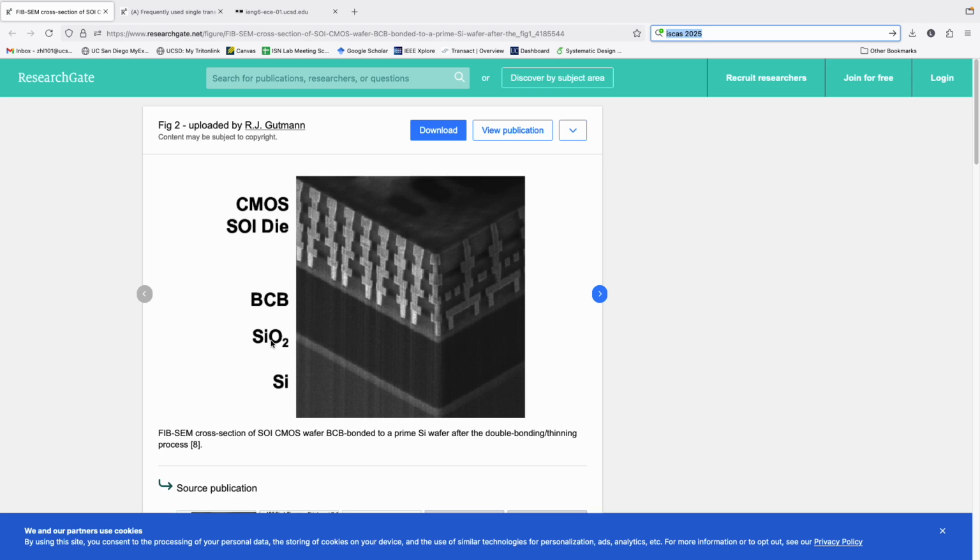On the bottom is the silicon, and this is the silicon dioxide for insulation and whatnot. Up here, these Lego-like ladders are the cross section of the metals that you build in circuit. If you think about them, these are literally just metal strips laying on top of each other, from metal 1, metal 2, all the way to, say, metal 5, metal 7 in this case.